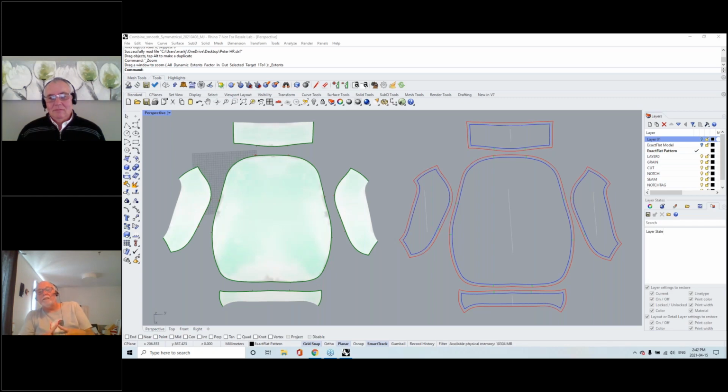So you would have probably an unacceptable error, especially if you're going round to meet something at the other side. As you noticed on the headrest, I went round the headrest and it met again on the other side. Now, there are ways of dealing with that. The first thing is don't do a complete path. Start from a central point and go clockwise and anti-clockwise. That halves the path length.